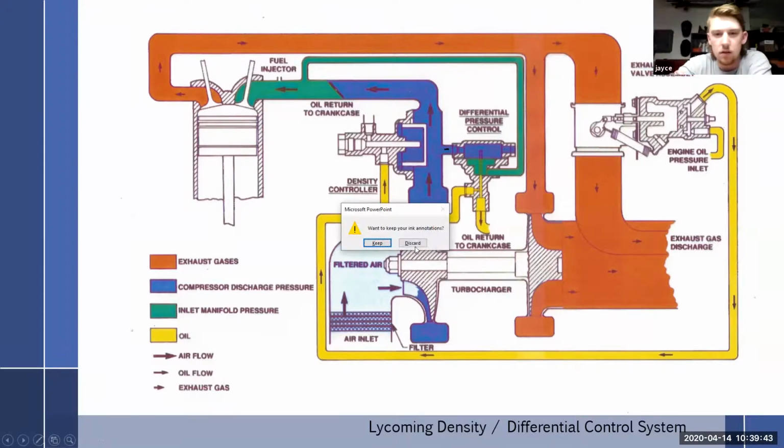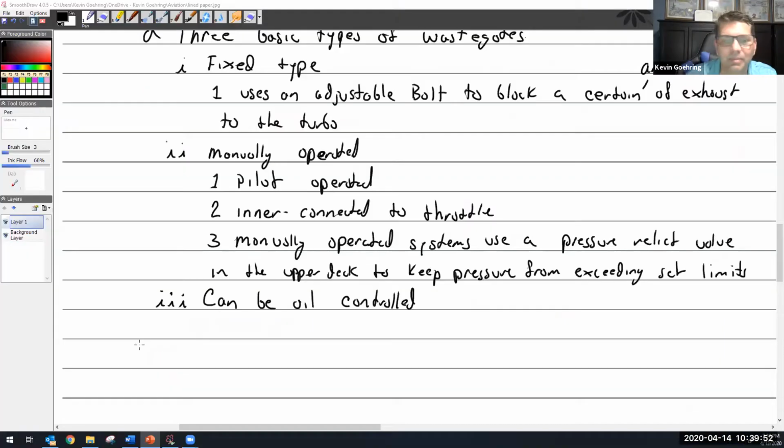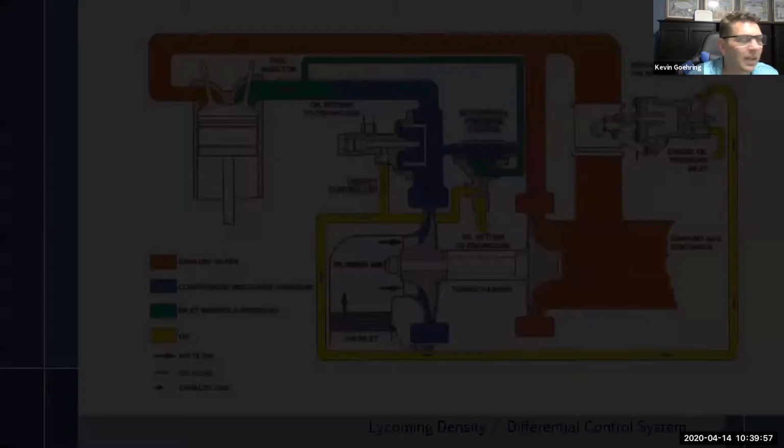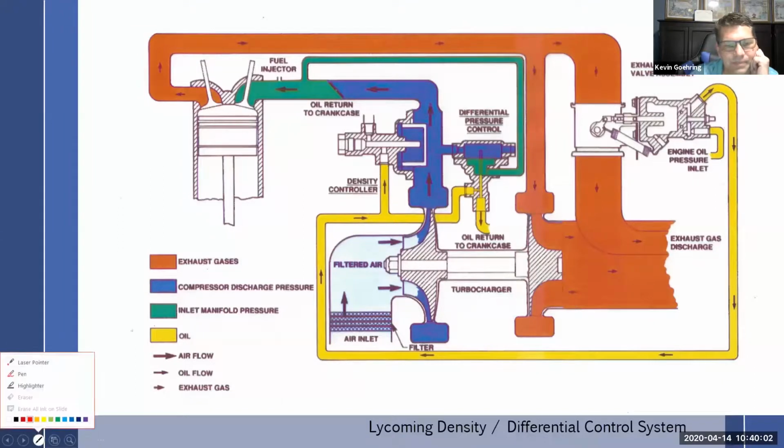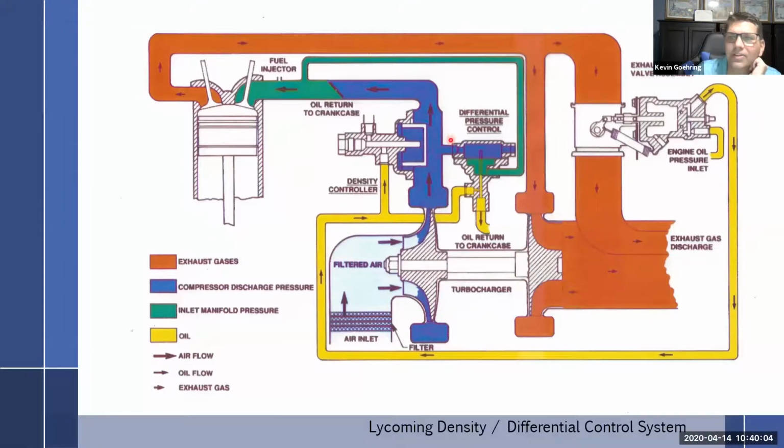So how does the differential pressure control deal with the critical altitude? It doesn't know anything about it. Okay, but you said it kind of deals with that? No, let me go back to that. That was a really good question. I didn't finish this. If I want to follow through on that thought process, because I like that question: this over here, I just want density. That's all it keeps saying. Well, that's its job. The differential knows nothing about density, nor does it even care. It's the furthest from its mind.